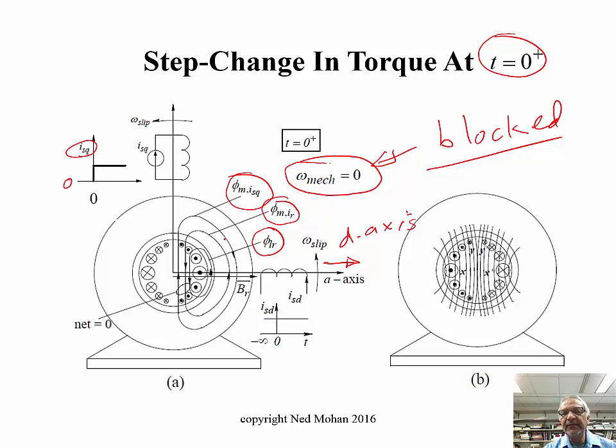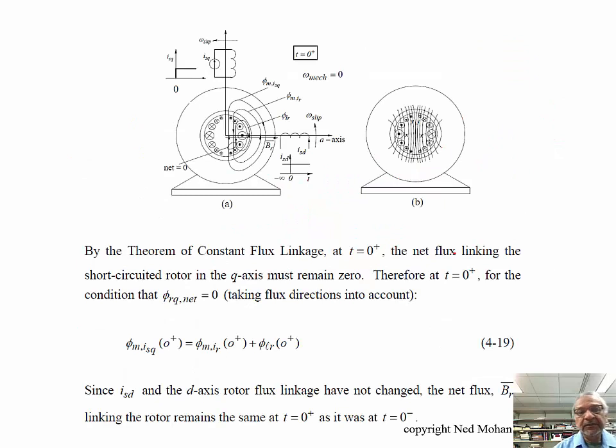And you may ask why this sinusoidal current density distribution in these bars. Well, you can see that if you take a sort of a coil made up of X and X prime, it's cutting more flux lines, so it needs more current. And similarly, if you take a coil made up of Y and Y prime over here, it's cutting less flux lines, so it needs less current. So automatically, the current distribution in these rotor bars is sinusoidal. Okay.